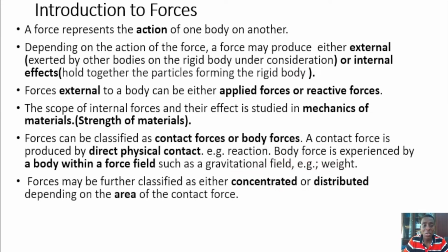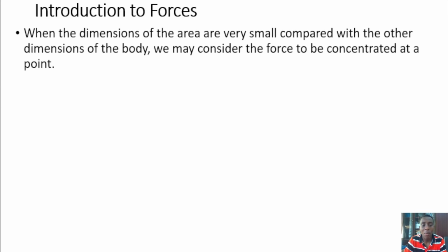We can also classify forces as concentrated forces or distributed forces, depending on the area of the contact force. Forces which are contact forces can be further classified as concentrated or distributed. When a force is concentrated, it means the force is acting at a small area. When the dimensions of the area are very small compared with the other dimensions of the body, then we may consider the force to be concentrated.